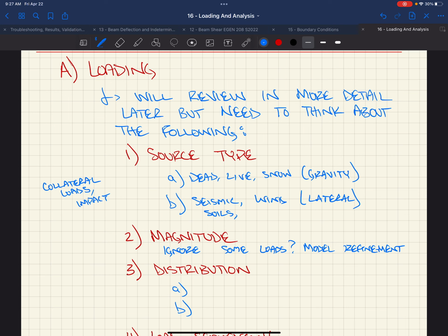if there was a connection between the shear strength and moment strength of an element, then you might want to consider, okay, I'm going to design it for this load combination. It might be the max moment, but that's tied to some shear demand also, right? And so then I design that member for the connection of those two, because for the capacity of the member, those things are connected in some way. If you're designing in steel or even in concrete, the moment capacity is independent of the shear capacity. You wouldn't want your member to fail in shear, and you don't want it to fail in moment, but those are independent.